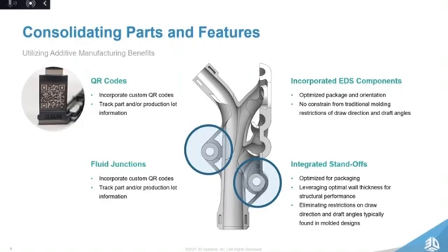And for full product traceability or control, things like QR codes are something that we've developed and been experimenting with, and can be incorporated as part of the additive manufacturing into individual components. The design of the code that we've developed has specifically been developed to have a real readable contrast, as you see on the picture on the slide there, with some element of translucency through the QR code to enable reading of the code itself. Next slide, please.